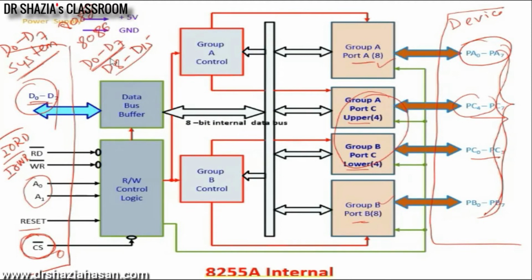So this 8255 is going to connect either to D0 to D7 or to D8 to D15. That means I can access only even addresses or only odd addresses. In the last class we discussed why, even if you have an 8-bit address, you can connect a maximum of 128 devices, not 256, if you have an 8086 processor. Why? Because it is an 8-bit device, so you are going to use only half the data bus. I cannot use both data buses simultaneously.